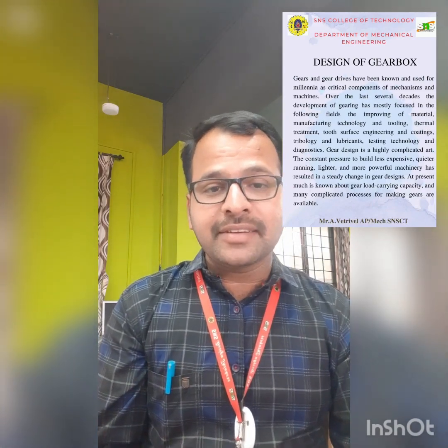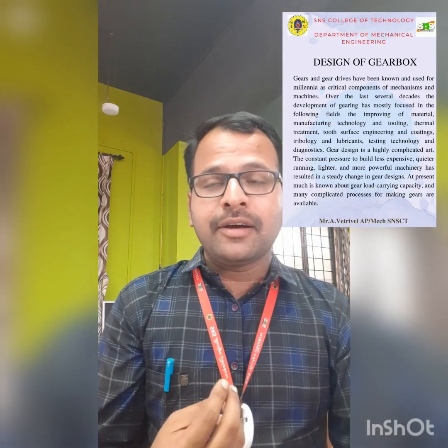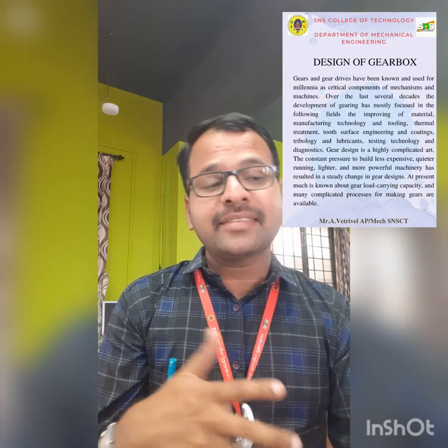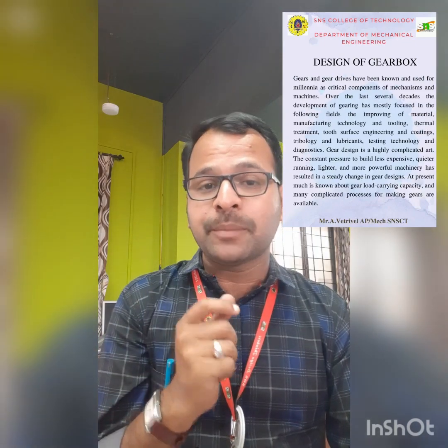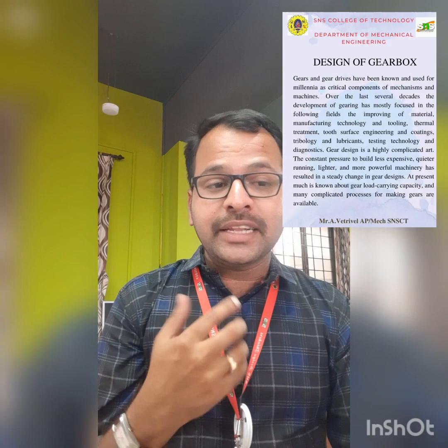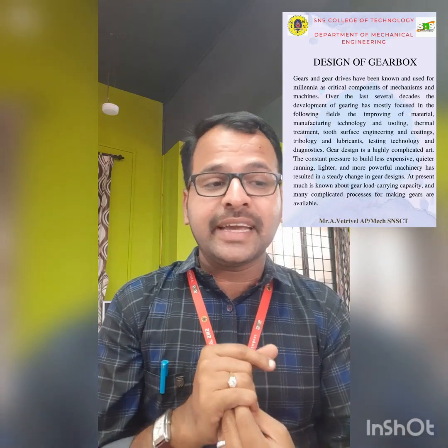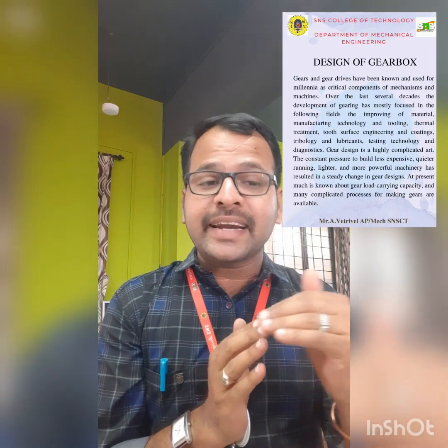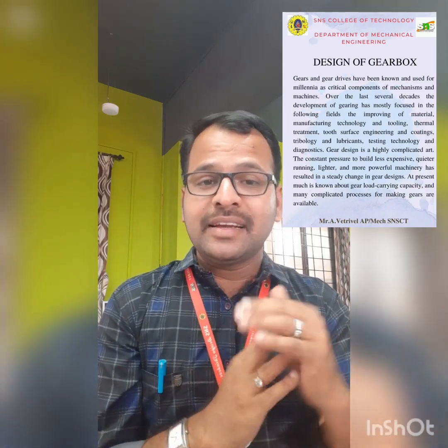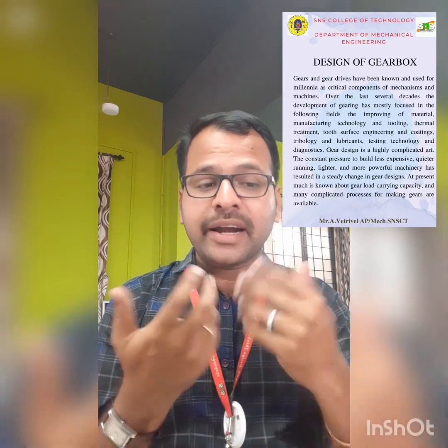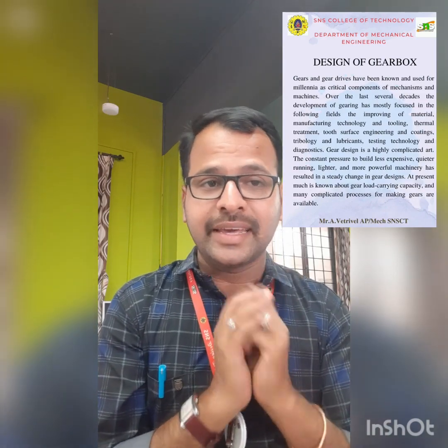The major functions of gears may be for setting the rotating speed, as gears can adjust the rotating speed of the power. Next, gears are for transmitting the power. The second function of gears is that they can transmit power with interconnected gears without causing slippage. Gears also change the torque or the power direction. So these are all the major functions of gears.